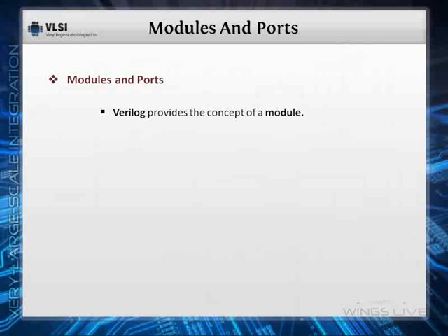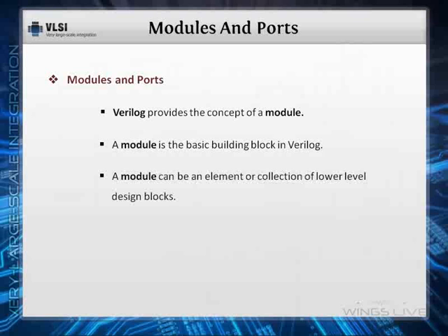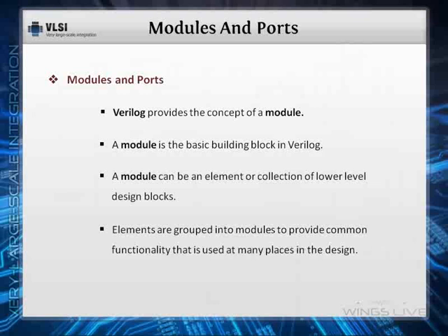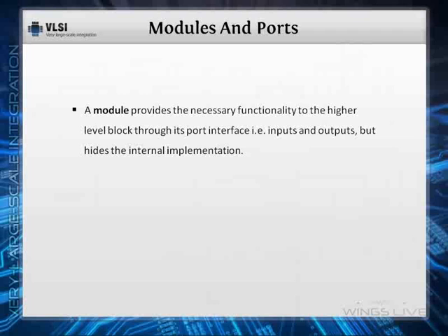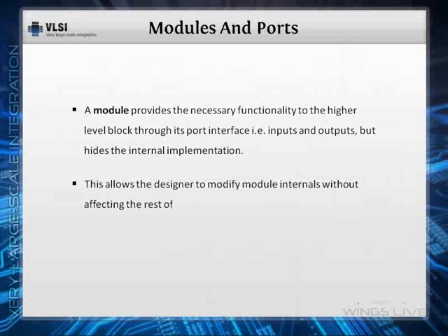Verilog provides the concept of a module. A module is the basic building block in Verilog. A module can be an element or a collection of lower-level design blocks. Normally, elements are grouped into modules to provide common functionality that is used at many places in the design. A module provides the necessary functionality to the higher-level block through its port interface, that is, inputs and outputs, but hides the internal implementation. This allows the designer to modify modules' internals without affecting the rest of the design.